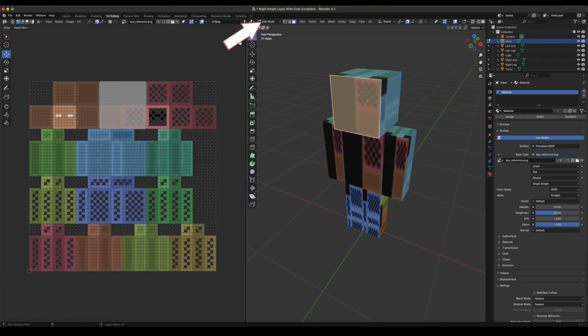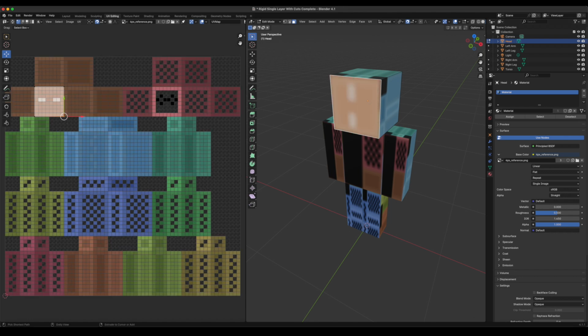Ensuring we're back in edit mode, with face selection, we select the first face, the model's actual face, that we're going to correct the texture map for. In the UV editor, select the Move function and set about moving the UV island to the front of the face and aligning the 4 vertices with each corner of the face texture. We have the texture mapped to the face, but its rotation is off.